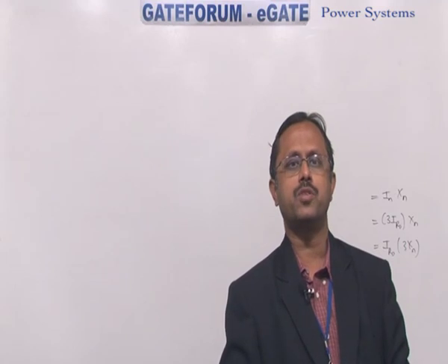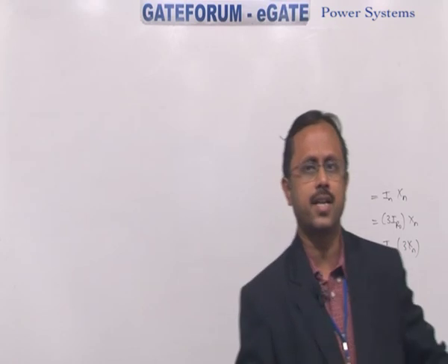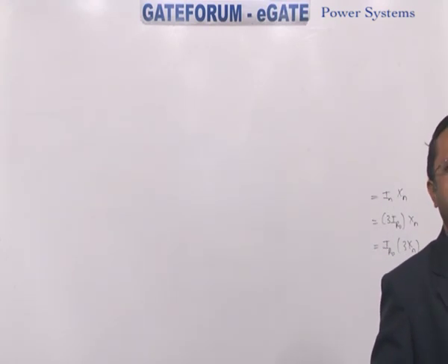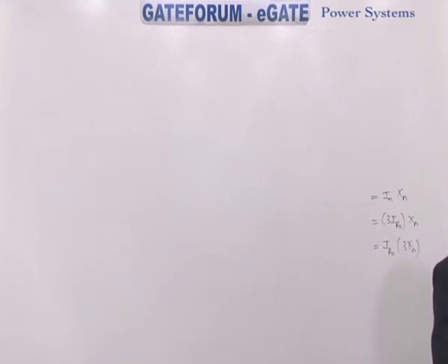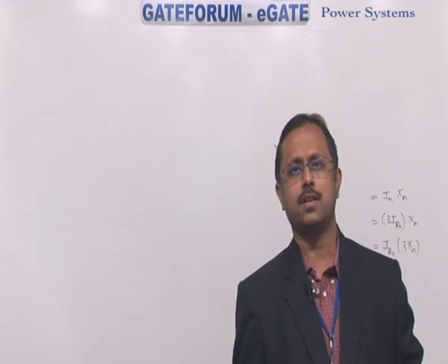Next question is by Vishwam from Agartala. Why is the damper winding disconnected in subtransient duration? Why is the field winding disconnected in transient duration? Only in order to decrease the fault current magnitude, no other reason.